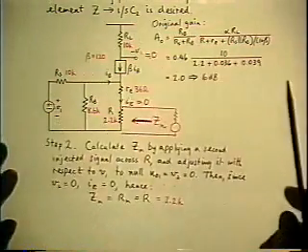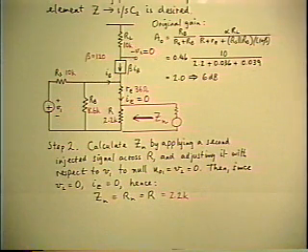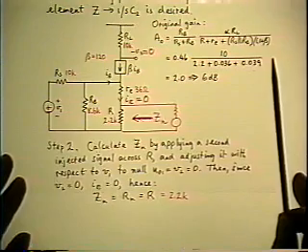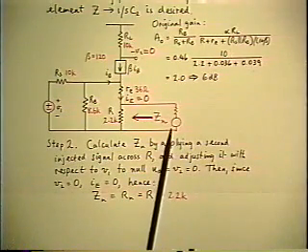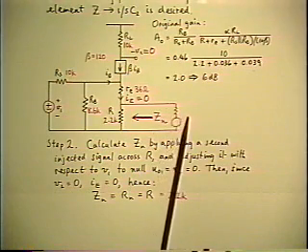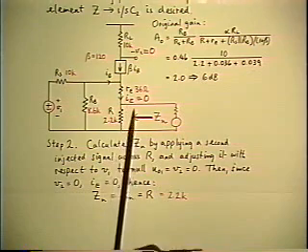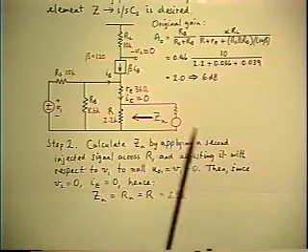Now the other one, calculation of Zn. This is the conceptually new one because we have to calculate this under the conditions of null double injection, which means that we have not only the second driving source, which we're applying externally in order to make the measurement, but the other input is now restored. So we have double injection.